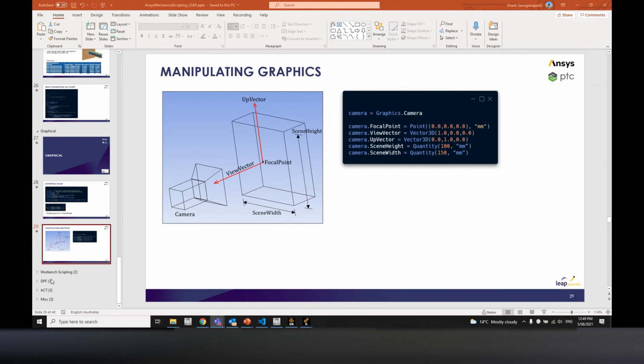Benjamin Wang, is it possible to control the results to show deflection above a given number? Say deformations above 10 mm or 1 mm. Yes, you can do that using legend manipulation, which I did not cover, but it's readily available in the help file. Okay.